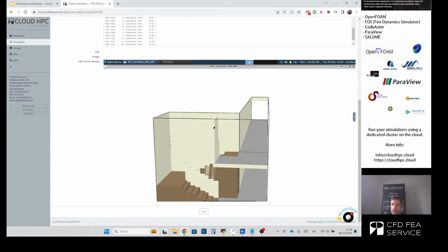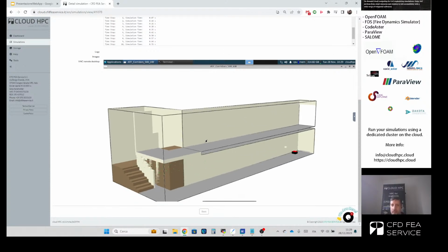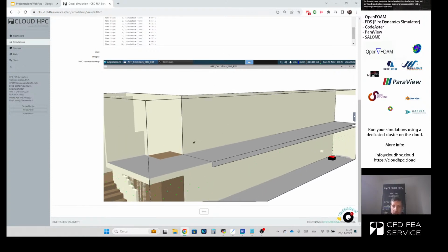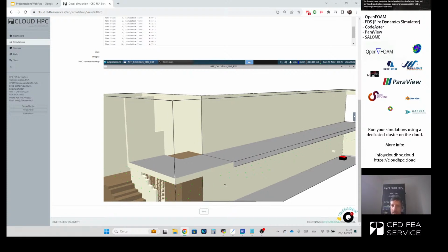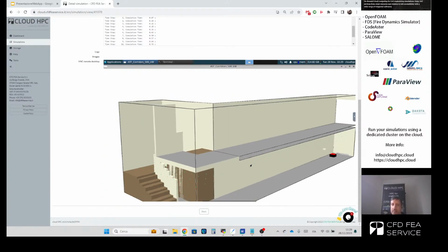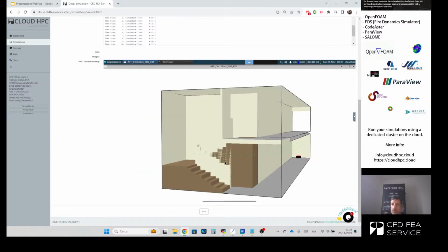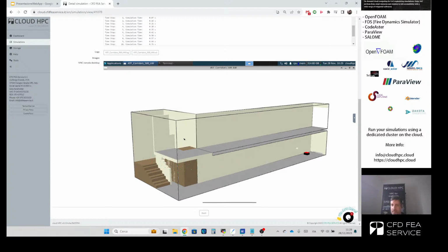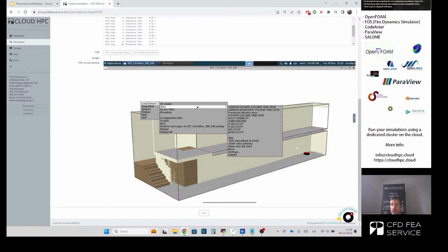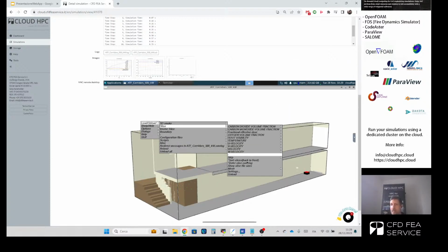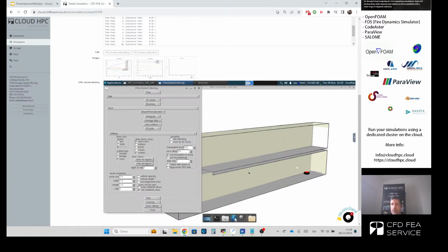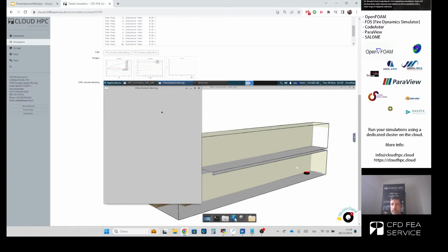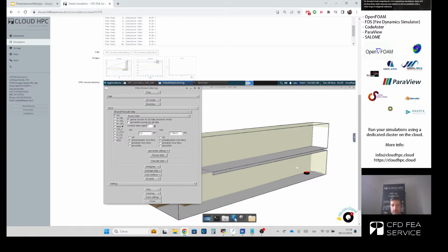This is Smoke View, as we can see earlier. If I zoom in a little bit, now you can see all these green dots. These are all the devices we are using to monitor the FED. So these are those devices I mentioned before. And now, before actually executing the simulation or having a look at the results, as I said before, we are going to go to settings, expand bound data.